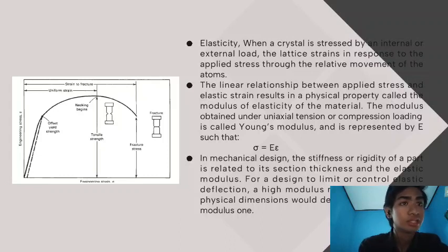If the elastic constant of the stronger material does not compensate for the reduced stiffness due to reduced section thickness, this could adversely affect the stiffness of the component. It is also important to note that for some alloys, the elastic modulus does change with the level of strength.